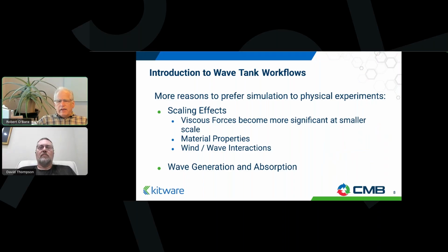Besides the fact that they can be expensive and take up physical space, another reason to prefer simulation is that there are certain aspects of WaveTanks that are very difficult to scale. If I'm reducing something from an ocean size to something in a limited space, some things just don't scale properly. Viscous forces is one of the major ones.